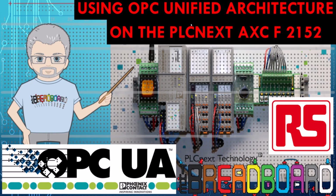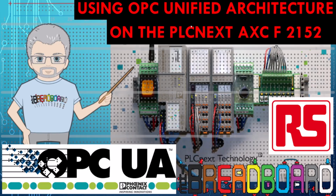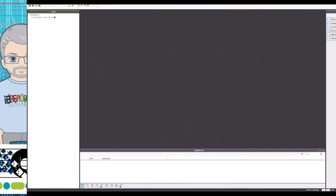Now, in order to help with the demonstration, I'm going to connect a panel meter to the analog output so we can show the voltage being output on one of the DACs of the analog I/O module, as we'll set it up as 0 to 10 volts. We'll also be utilizing the potentiometer that is part of the starter kit and some of the digital I/O switches, so that we can have an understanding of accessing all of these different things.